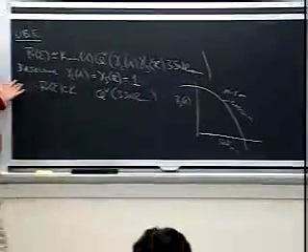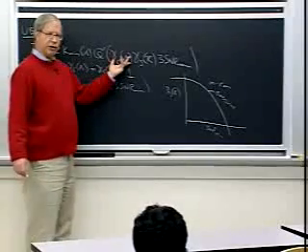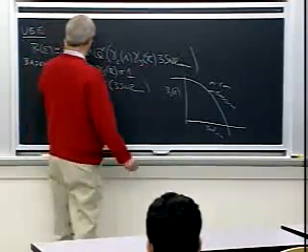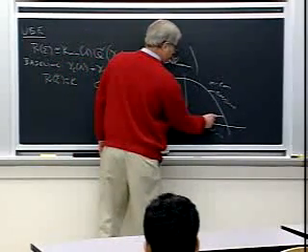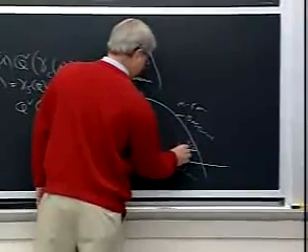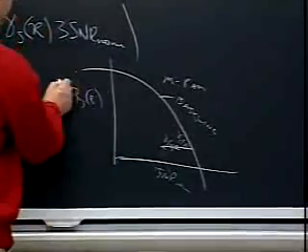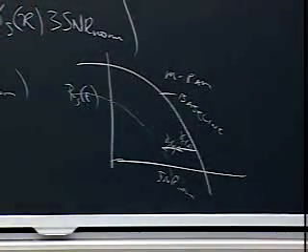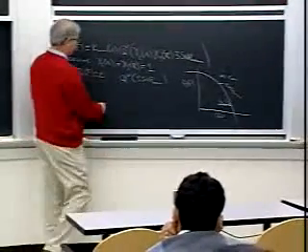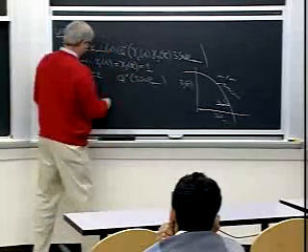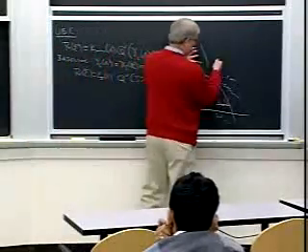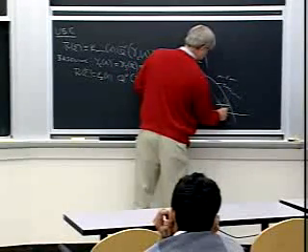And now we've got everything separated out in a nice way, so that if somebody gives us a lattice with a certain coding gain and a region with a certain shaping gain, those both just add up as gains. If that's all we had, forget the coefficient, we would just move to the right here. They would give us effective reductions in required SNR norm by the coding gain of the lattice and the shaping gain of the region. Okay, and we'd get the same curve moved out over here. Again, as in the binary case, typically we're going to get a larger number of near neighbors, leading to a larger coefficient out here. We want to normalize this per 2 dimensions. Per 2 dimensions, it's only 4 for the baseline, but in general, we're going to get a Ks of lambda, the number of nearest neighbors per 2 dimensions, which is going to raise this a little, and that will lower the effective coding gain down here.